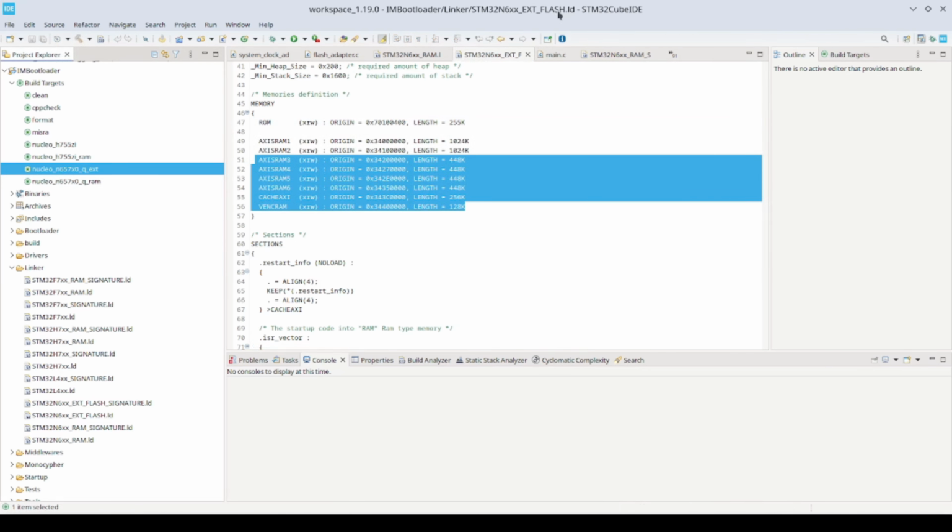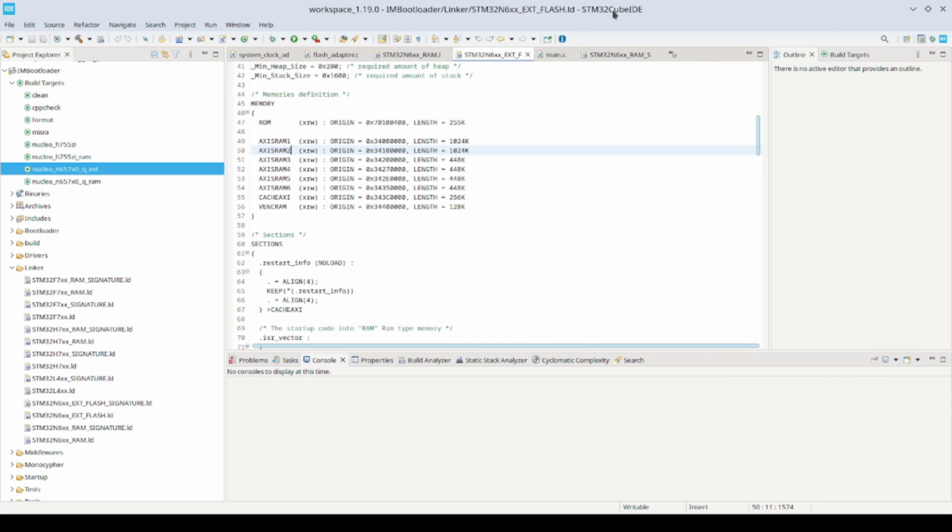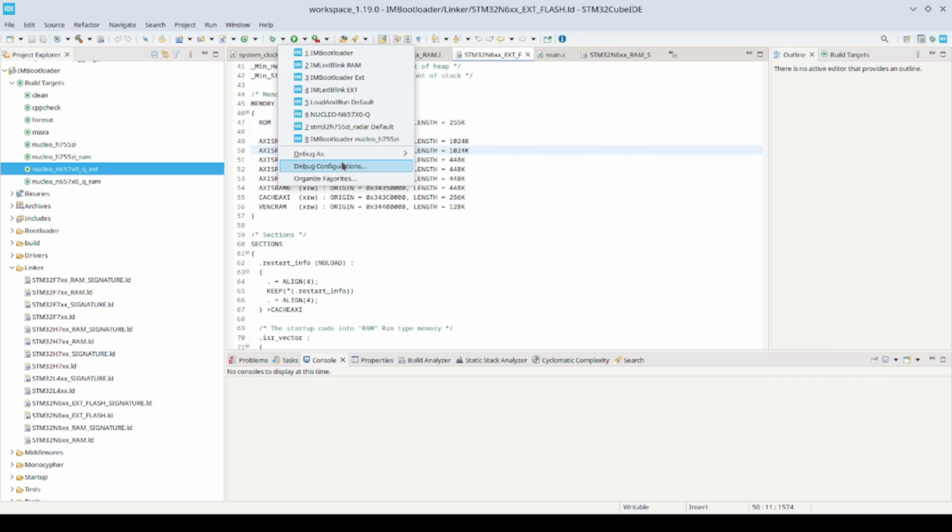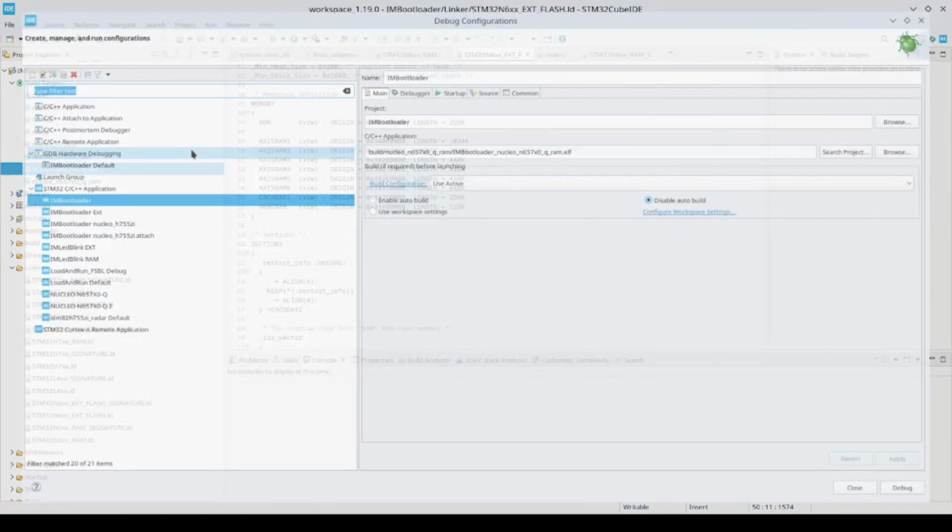To be able to do this, you need STM32Cube IDE. When I worked on this, the standard OpenOCD did not yet support this microcontroller. After setting up the IDE and ST-Link, you need to flash the first stage bootloader to RAM. Make sure the jumpers on the Nucleo board are set to debug mode.